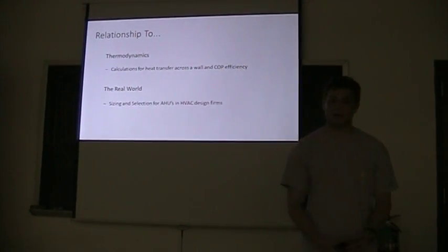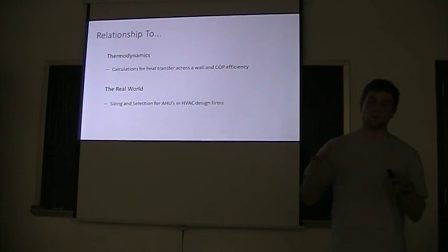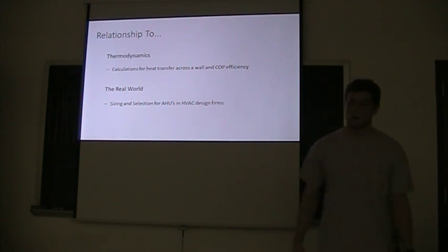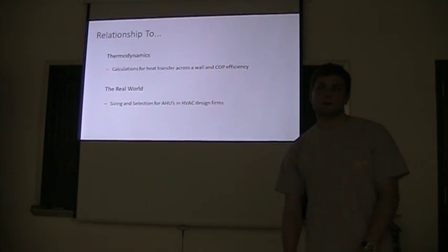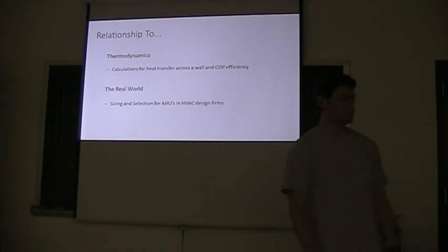If it was a 2-inch gap instead of a 1-inch gap, I don't think it would actually increase it. Going from 1 to 2 wouldn't double your resistance again, because you're not initially adding convection heat transfer in between the two walls. You're just extending the distance that the convection would happen. So it would probably only increase around 20-30%. I'm just guessing though. I feel like you should probably just leave it at 1. There's probably a happy medium, so that's an answer. Any more questions?